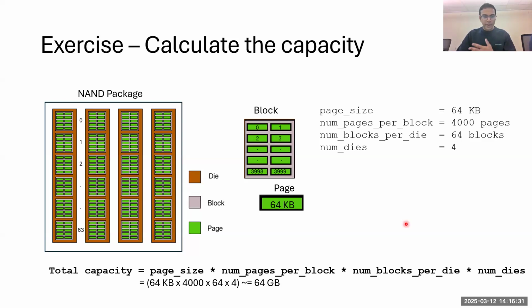Let's say you write data to a portable solid state drive, and then you disconnect it, and sometimes you won't reconnect it for months or sometimes years, and then you connect it after several months or years, and you'll still find data on them. So you would have to look at the spec on those SSDs to see how long they would retain data without having to be refreshed. Normally they are months or years, and I don't have exact numbers. It would depend on the type of NAND.